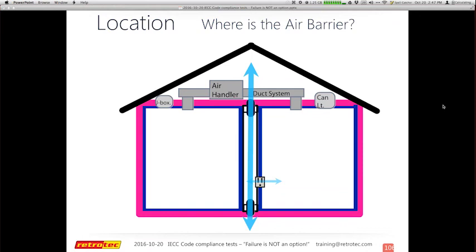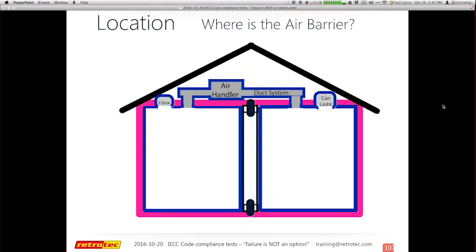I do know that many people are using electrical boxes and other different things and making them airtight. Those are much more requirements that are out there. But in general, there's a lot of stuff that we test for with the blower door that you might think comes in with the duct system, but my leakage to outside is directly connected to those kinds of penetrations.